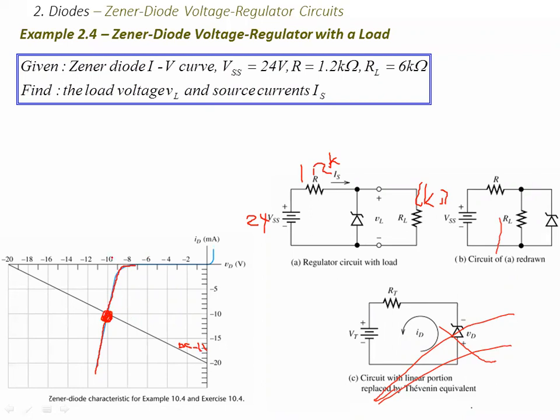It means the diode reverse voltage is what? Is 10 volts, right? Can you see that? For this kind of diode given, it means this is its operating point, the intersection point of the diode characteristic curve and the DC load line. That will be the intersection, right?